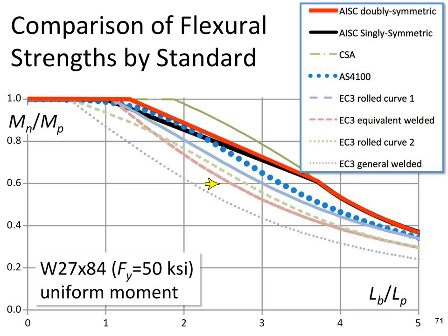So when you look at this picture, you might say, wow, the AISC is so liberal and the Eurocode is so conservative. But actually keep in mind that the AISC was very conservative with their C sub B factor, where the Eurocode was very liberal with it. So I think in the wash, as long as you've got some moment gradient, which is almost always the case, the specifications are really giving essentially the same amount of capacity.